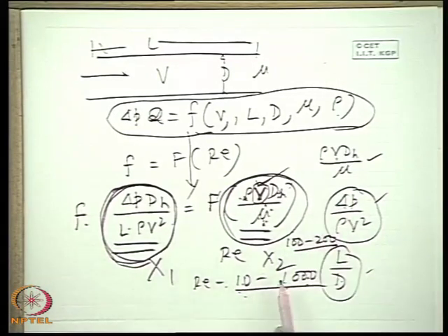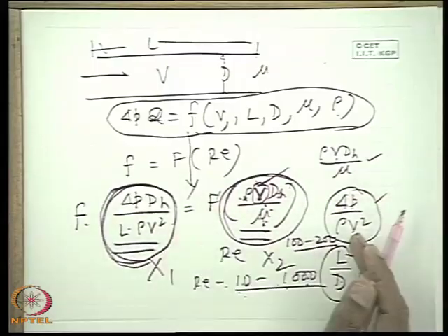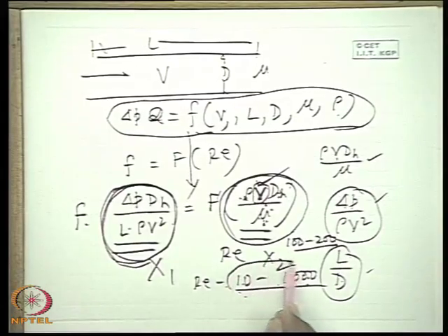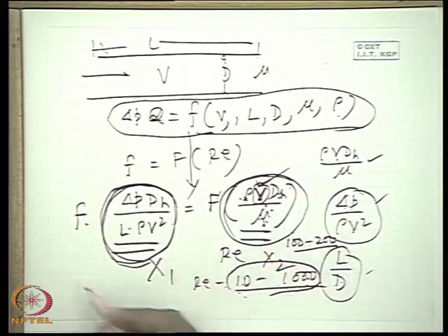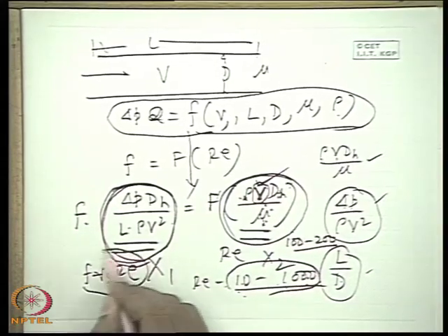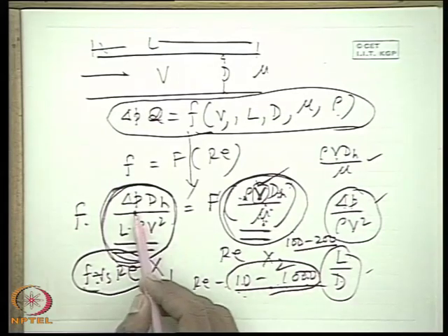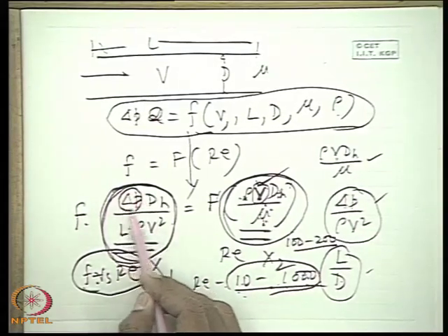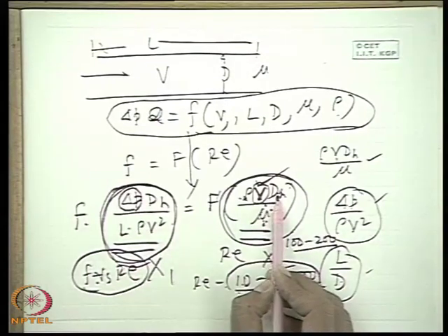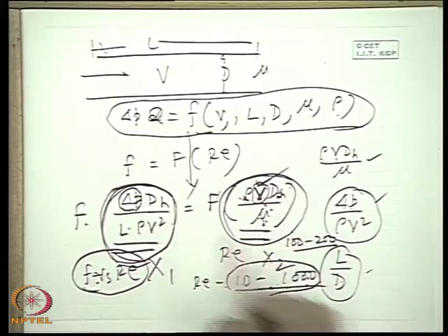From the similarity point of view, if a system prevails under two different conditions so that the range of Reynolds number is the same, then the friction factor versus Reynolds number curve will be equally applicable in both cases. The only thing is that one has to read the friction factor from a given Reynolds number and accordingly decode for his pressure value, depending upon his value of diameter and velocity, whatever is prevailing in his set of conditions.